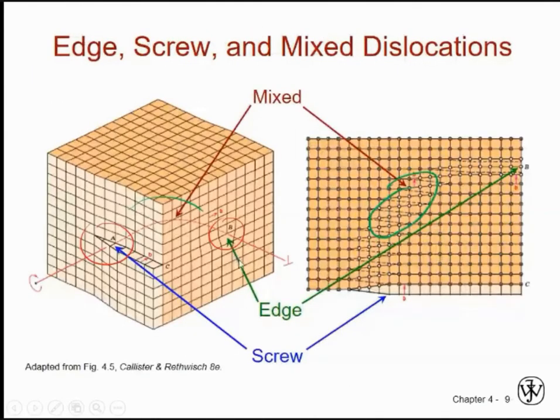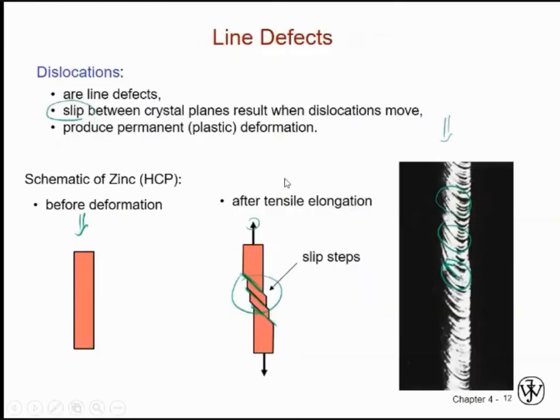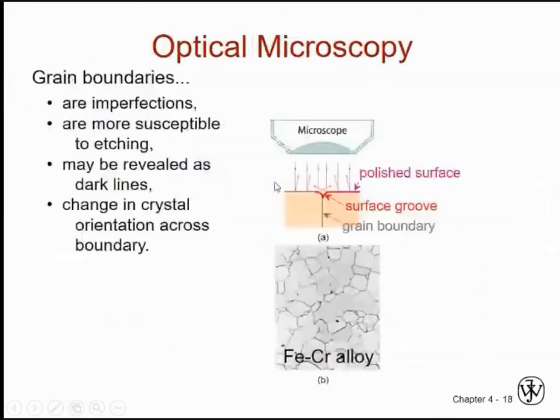In screw dislocation, where is our dislocation line? So this tearing, this shear ends here. If you just draw this line over here, that is the dislocation line for screw dislocation, and the Burgers vector is parallel to the screw dislocation line. Now let's return back.